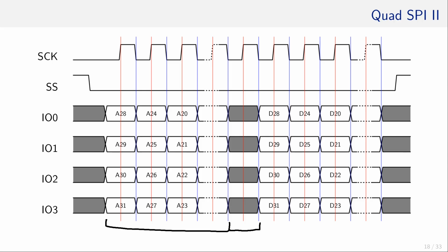So the serial peripheral interface becomes a bit of a mix of a serial and parallel data transfer, essentially increasing the transfer speed by 4 times what could originally be achieved through the traditional SPI. As you can see, the data is sampled at the rising edge of the clock marked in red here, while the falling edge in blue allows to set up the new data.